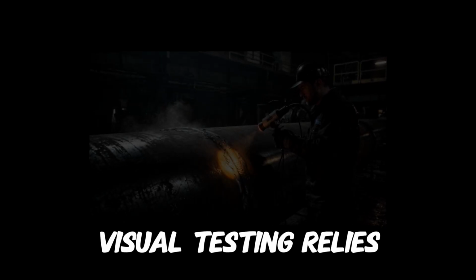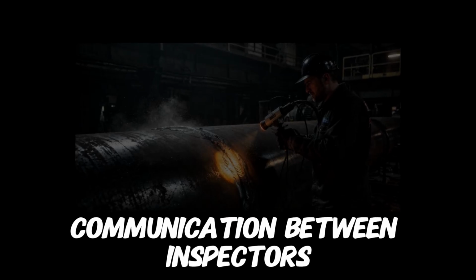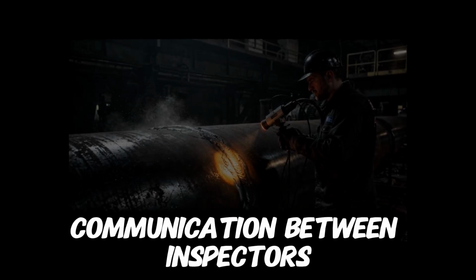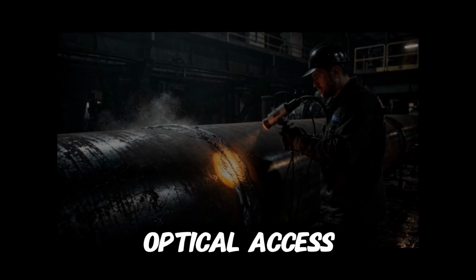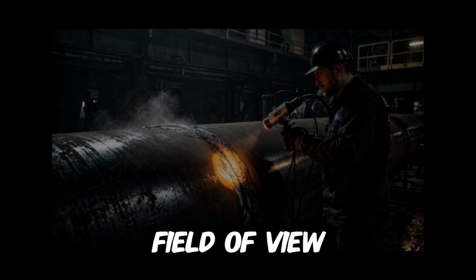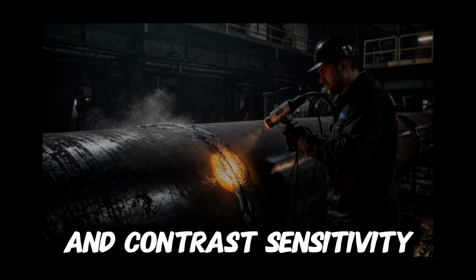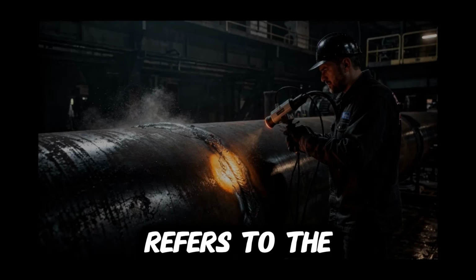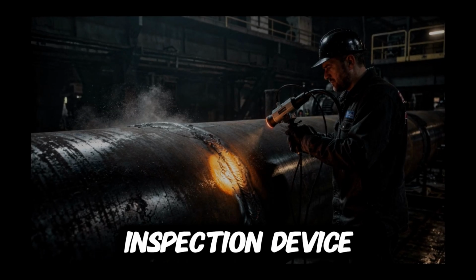Visual testing relies on standardized terminology to ensure consistent communication between inspectors, engineers, and quality personnel. Key terms include optical axis, field of view, resolution, depth of field, and contrast sensitivity. The optical axis refers to the straight line along which light travels through an inspection device.